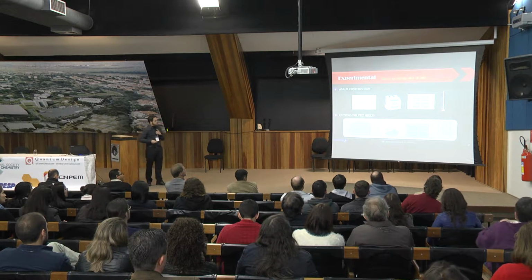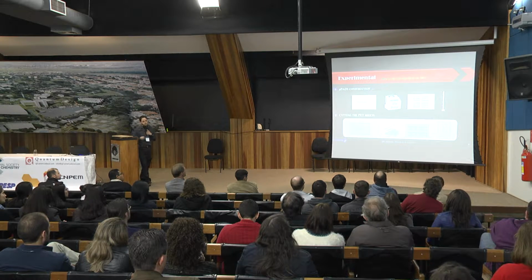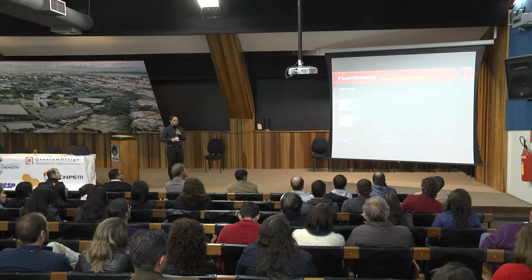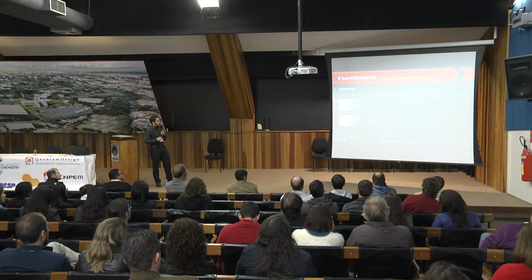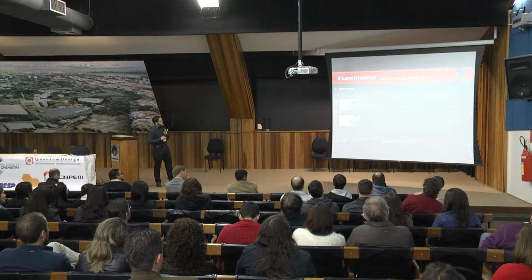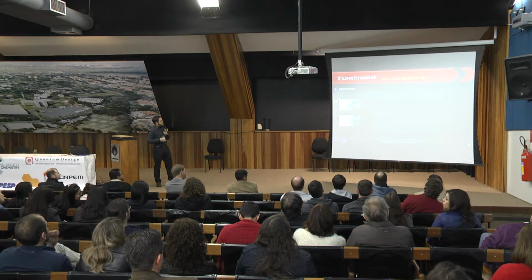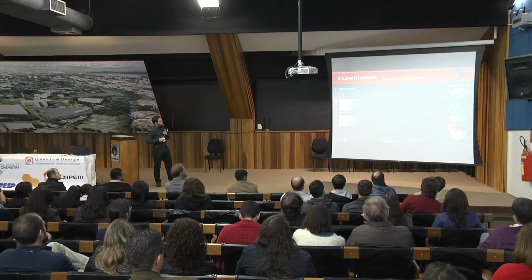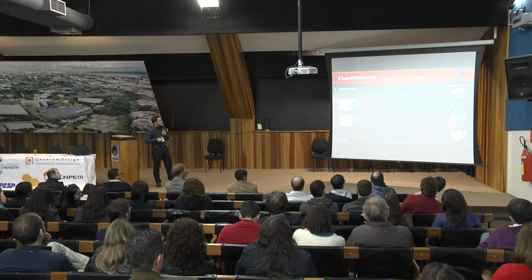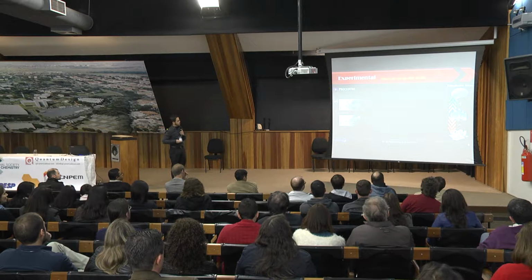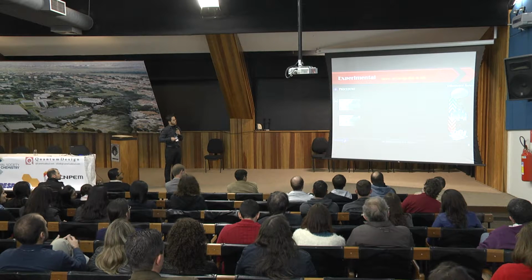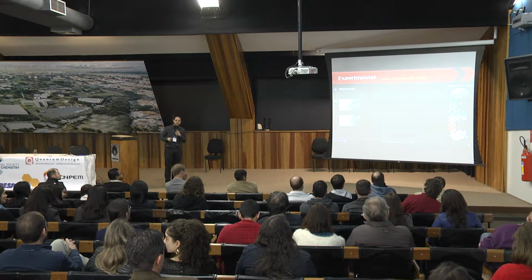And for the PET sheets, we cut them with a Silhouette plotter, but we could also cut with scissors. The procedure to fabricate that closed device by triboelectric effect was simple also. First, we use two pieces of PET and rub them with two different materials. We rub one PET on Teflon, which is more negative in the triboelectric series, so the PET will become positively charged. And we rub the second piece of PET on PMMA, which is more positive, so that PET will become negatively charged.